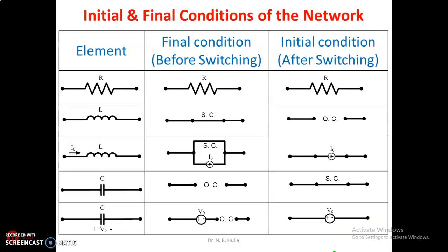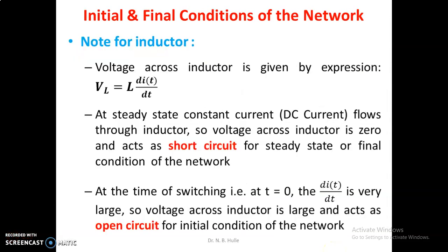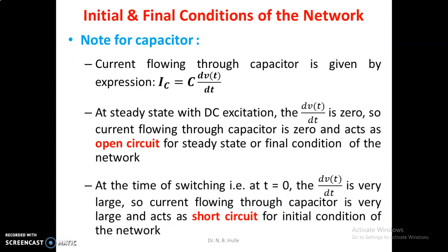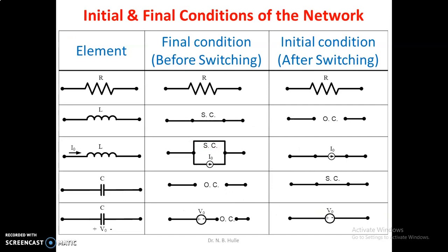Now try to understand here. During the final condition, the capacitor acts as an open circuit, and during the initial condition, the capacitor acts as a short circuit, as I discussed in the previous slide. During the steady state, it is an open circuit, and during the switching time, it acts as a short circuit. That means during the initial condition it is a short circuit, and during the final condition it acts as an open circuit.